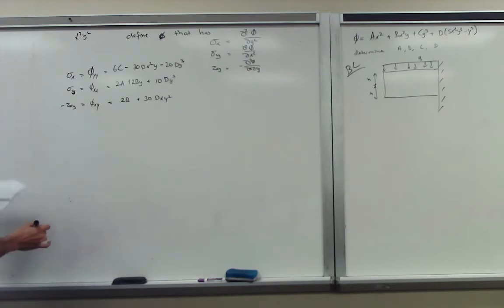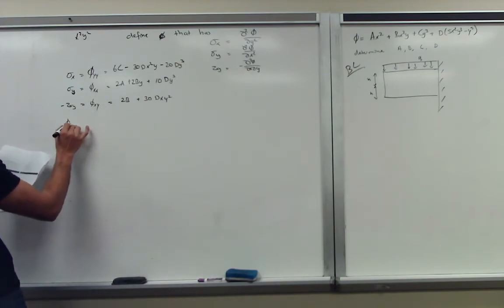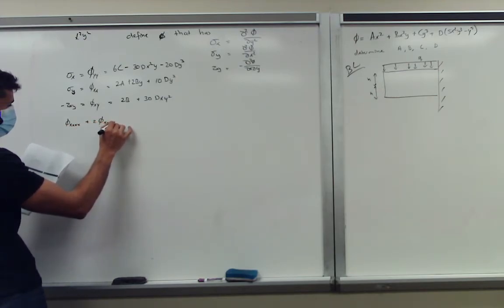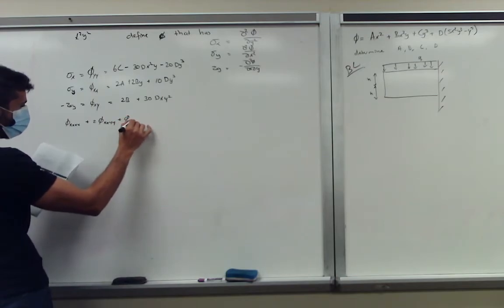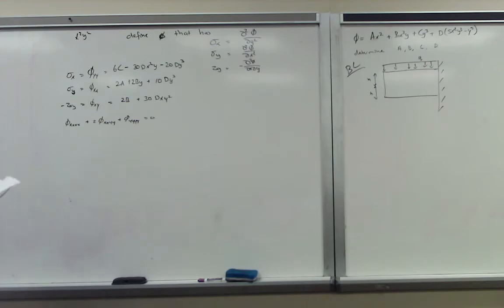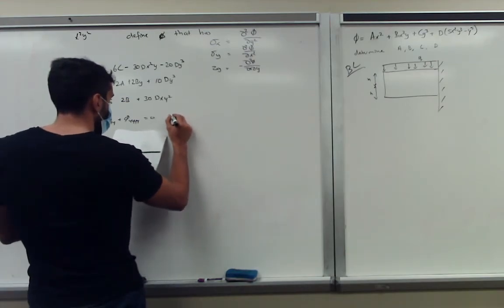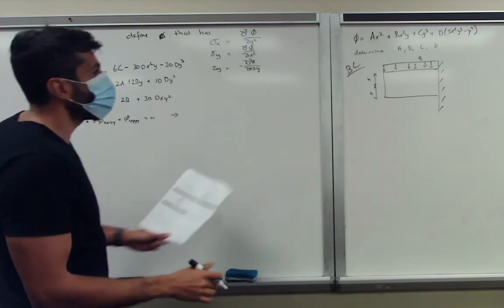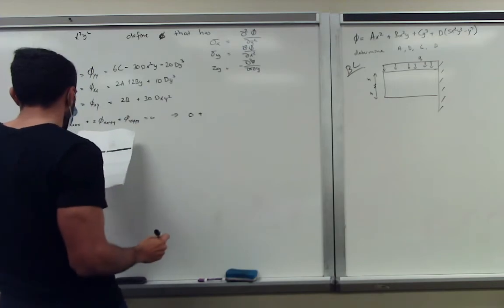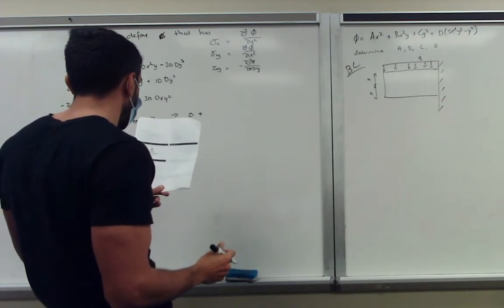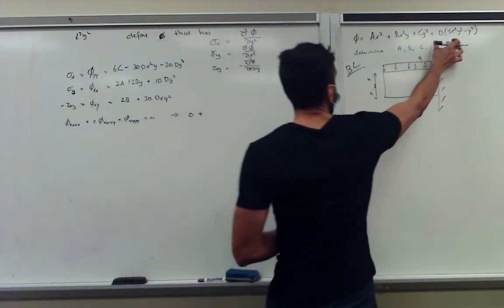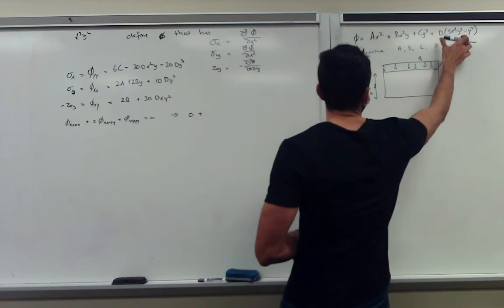And then, of course, our biharmonic equation must be satisfied as well in order for the solution to be correct. So if you do that, there are no fourth powers of x, so that's 0, plus 2 times phi xx yy. So there is only this term that satisfies this condition.